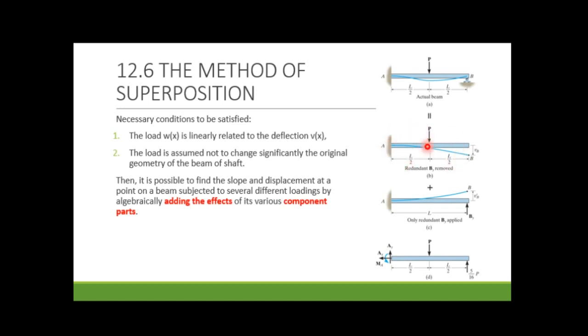By using this point force, I can calculate the deflection at point B. Also, I want an additional system at point B. Remember that we have a reaction force at point B. I put By instead of B, which we don't know, and use the deflection with respect to By. If we combine these two models, we can obtain the whole system.